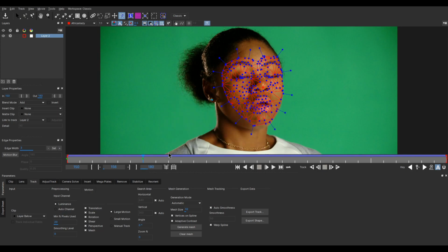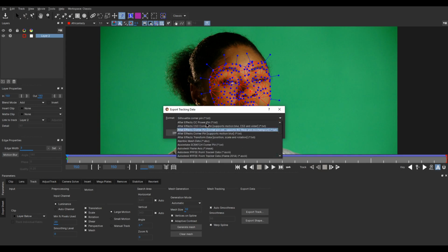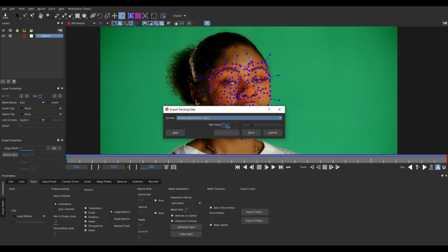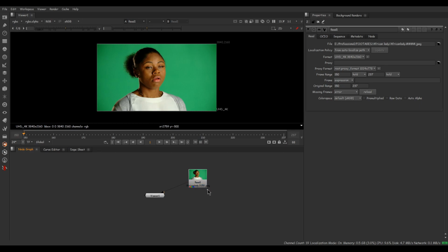Okay, here we have the keyframe. I'm gonna delete it. Come back to the first frame. Okay, a keyframe was added while we were editing that vertices. You can edit the reference frame also here, like which is the reference frame for your camera. Now I have saved that and I'm gonna import that alembic data into Nuke using a read geo.